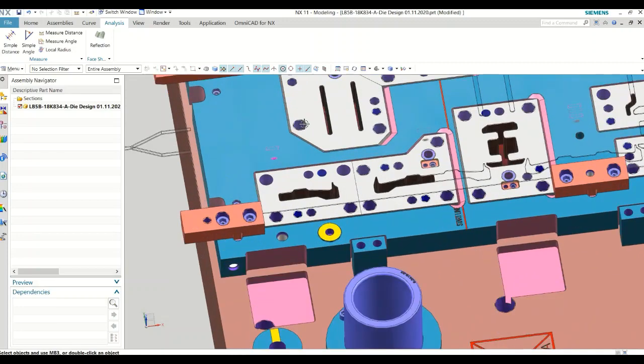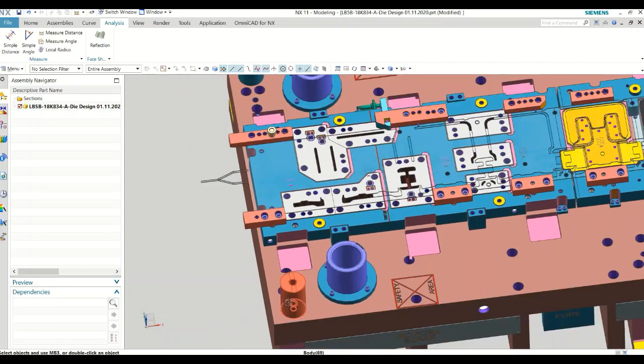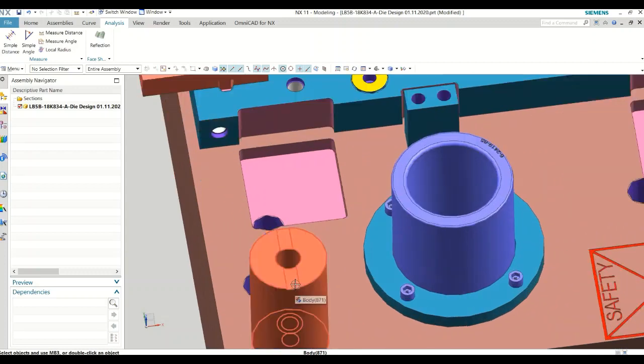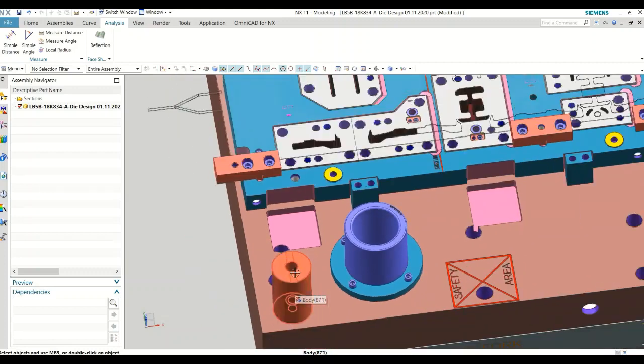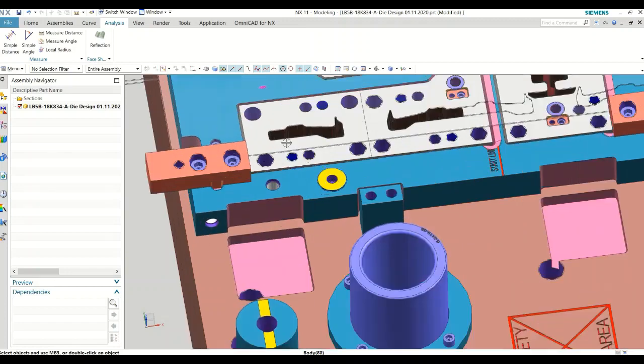Even though the groove is 1.27 mm deep, we sometimes keep it at 1.3 or a little more, so that it does not hit, just kisses. When it hits, it means you are going to add more pressure, more tonnage. Just kiss it, no more pressure.